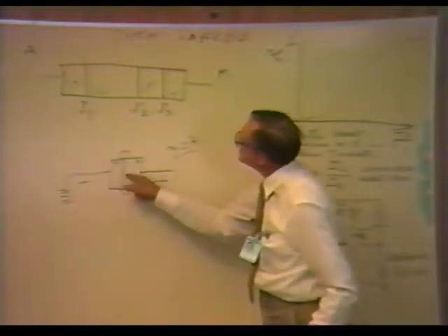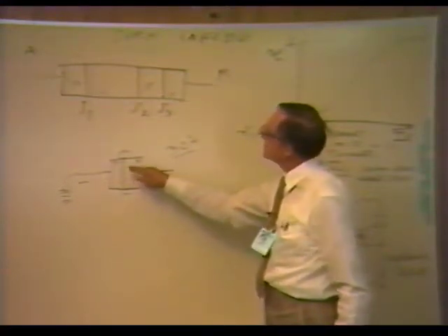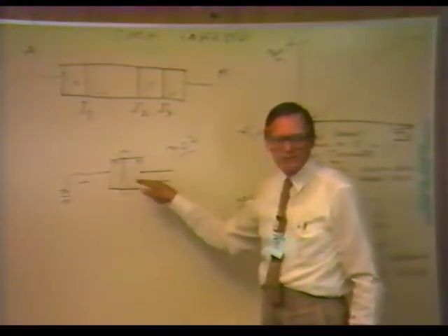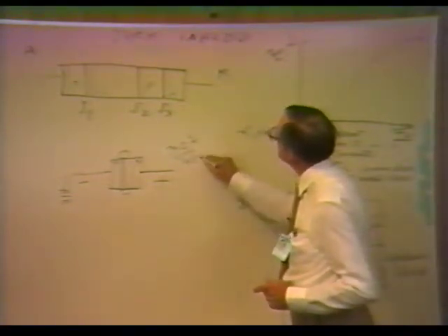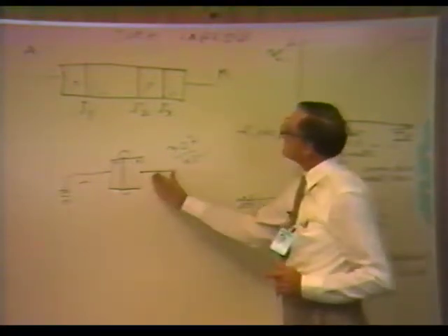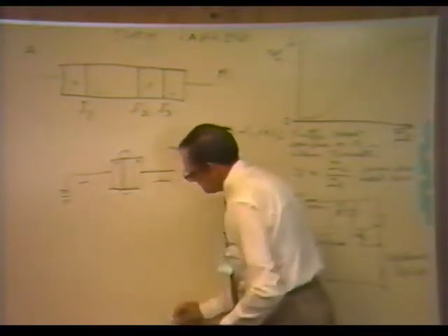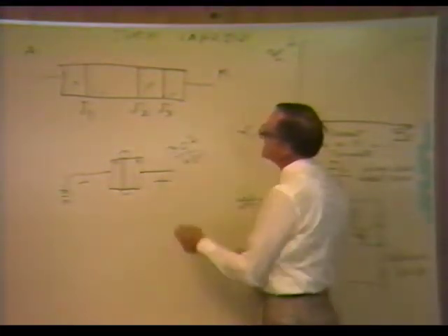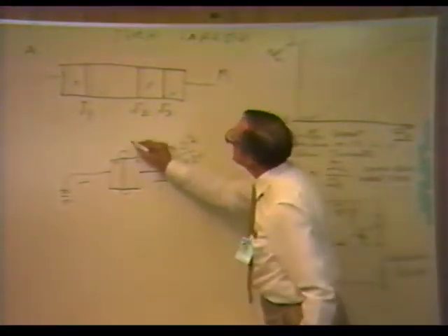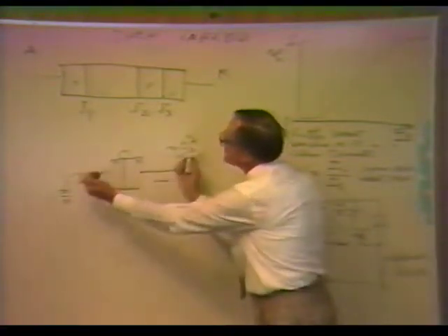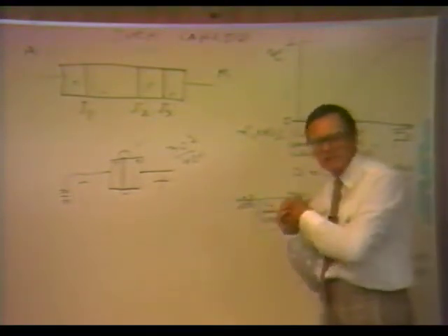Now, since there are no carriers in here, I can sustain that 30 volts because the junctions have been doped to withstand 30 volts. Now, what happens when I raise that? Let's say I go to 40 volts. Okay, when I go to that much, now the doping profile is such that it's going to sustain, it's made to sustain about 30 volts. Now, as I go up to 40 volts, this field expands. And it'll expand to 40 volts. That pulls back. But we have given a lot more energy now to the carriers, and they start tearing loose.